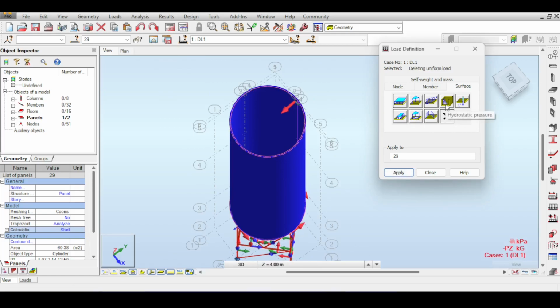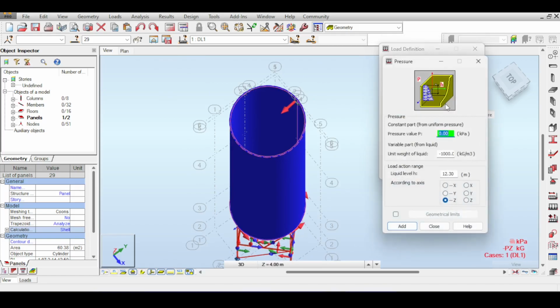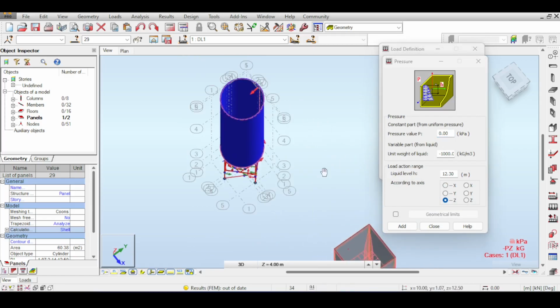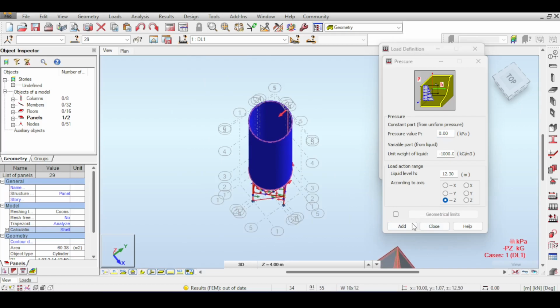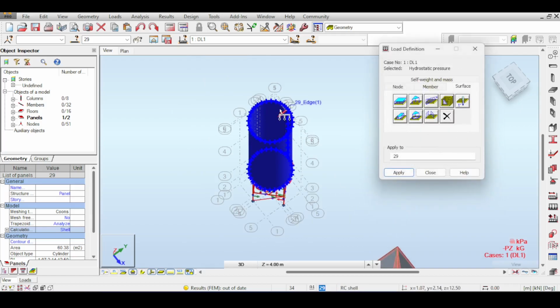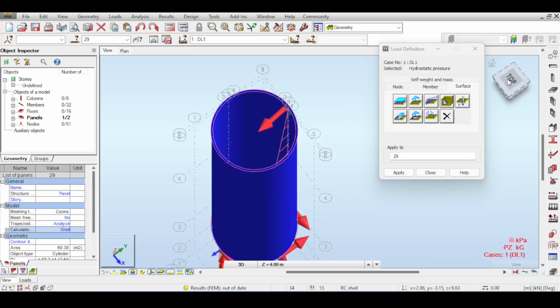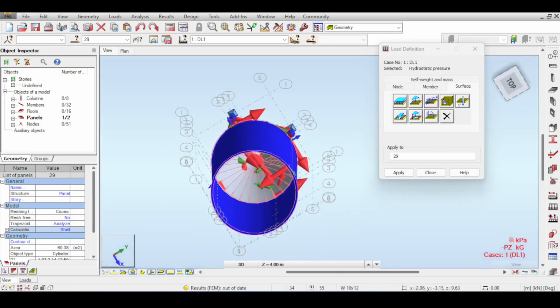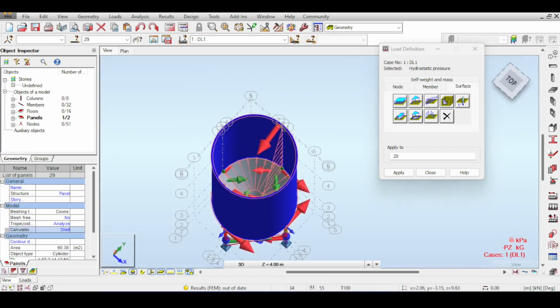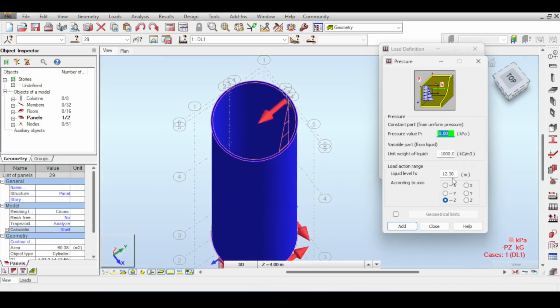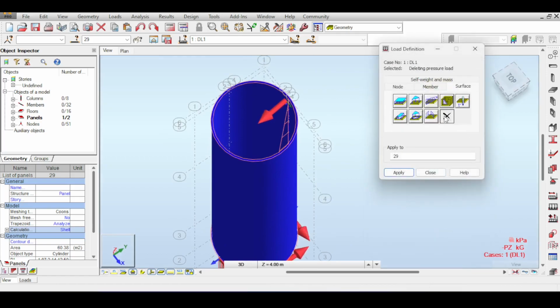So the other thing is triangular loads, right? If you click on hydrostatic pressure, you can define a triangular load by using a gamma here. Now, I have to calculate this gamma later. I will tell you how. But let me just show you something very cool. If you just add like this blindly, because I already have prepared this for you, side basically, and hit apply, you can see you can apply a triangular load which corresponds to a water load. And this could help you. Problem is that you have to define the height, and I think it's measured from the bottom.